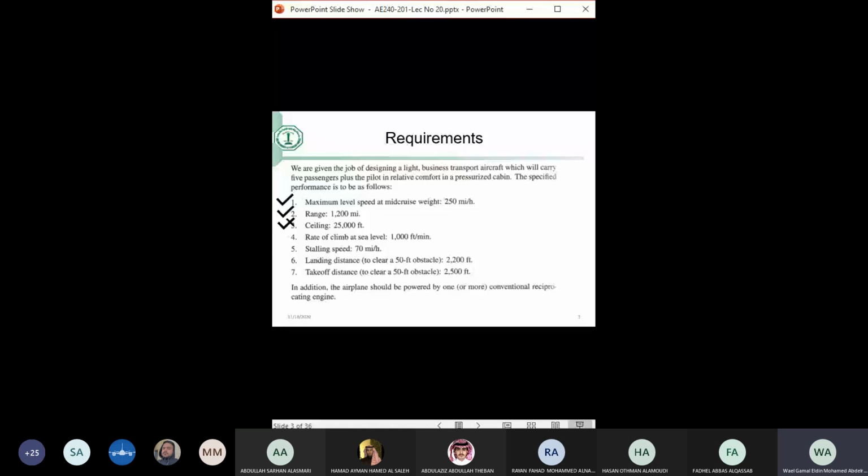Well, I will answer that. We didn't satisfy the ceiling anywhere. We didn't make sure the aircraft will go up to 25,000 feet. Okay, we selected the engine to give us maximum power up to 20,000 feet, with the hope that with the reduction of horsepower up to 25, it will still generate some considerable power. So we will check that later on. This condition we didn't completely check, although we could have, but we decided it will probably not be critical, just like the stall speed.